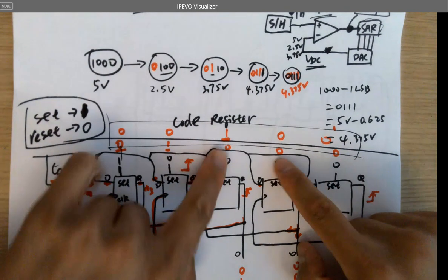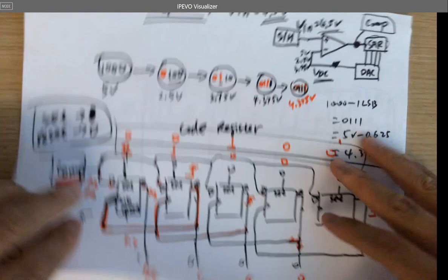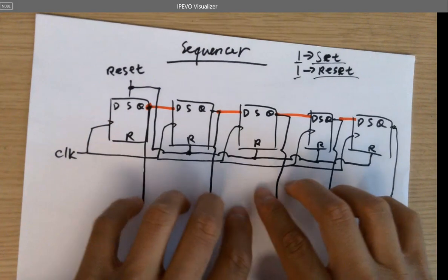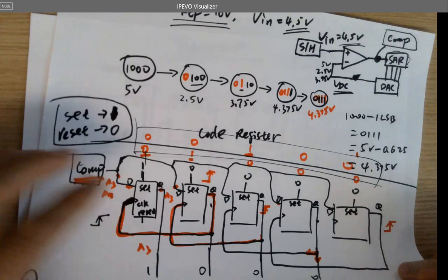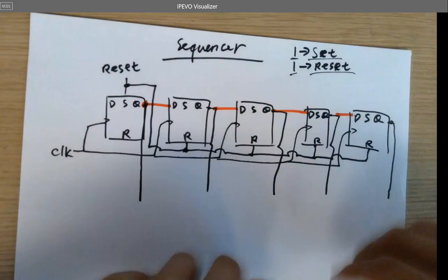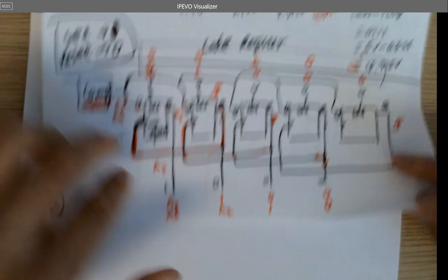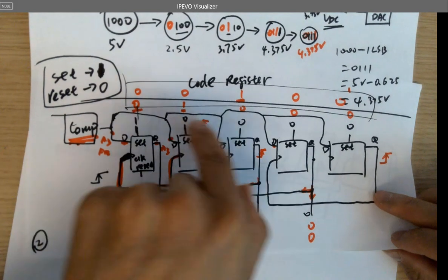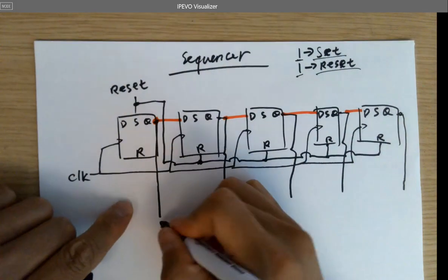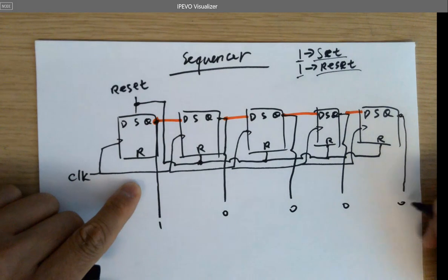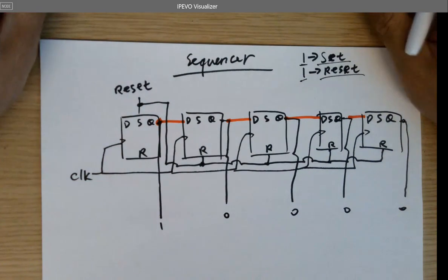And now we are designing that circuit to do it. So basically you have all these bits, these wires moving up, which are shorted to these 5 wires of the circuit on the top. I didn't draw the bottom part because it's the same circuit as the code register. So these are the wires feeding all the 1s and 0s over here. Now we want to generate a 1 0 0 0 0 at the very beginning, and then shift it to the right.